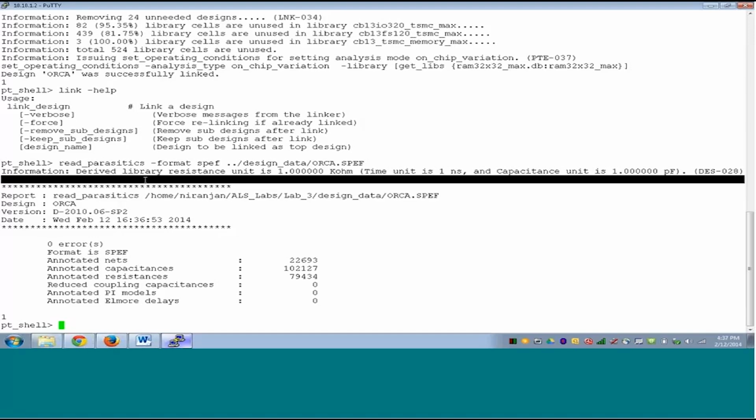If any such mismatch occurs, it means that the netlist that you have and the SPEF that is extracted have some mismatches, and most probably the netlist you have or one of these files needs to be updated. So the backend lead who is giving you this SPEF, or if you are the backend engineer, if you have a mismatch, then you need to make sure that you are taking the same netlist which you used to do the extraction. It is very necessary to do that. If you see errors like missing net in one of the netlists or this stuff.